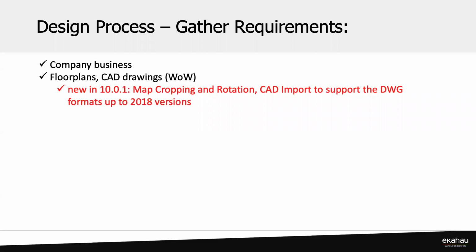And the second step actually is to collect floor plans. Ekahau supports several formats, so there is broad, wide support of graphical images that can be imported. And of course, the CAD drawing can make life very easy for you with the wall outline wizard, not to be confused with the workstation on wheels in healthcare. The wall outline wizard can really help you to draw in the walls automatically, and you can change the attenuation levels later on.